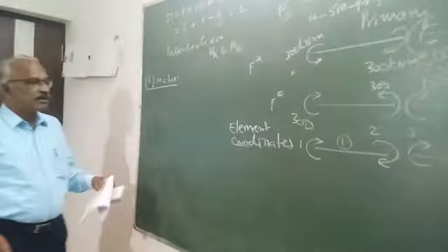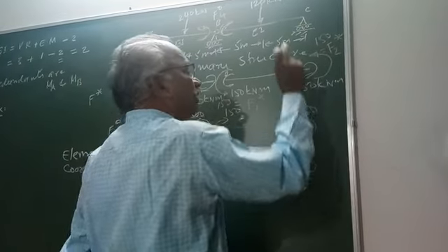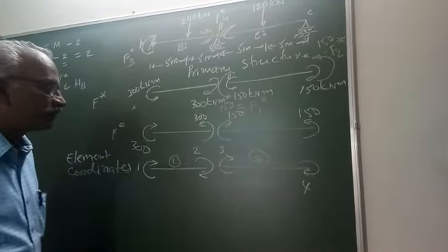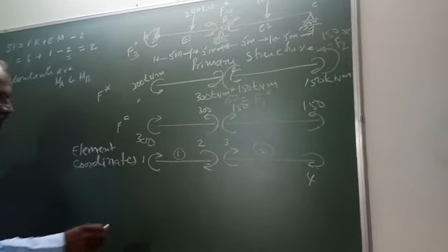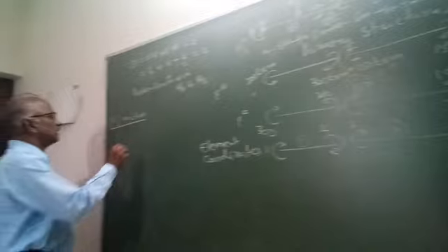We have to apply F1 star equal to unity and find out the values of the forces along the element coordinates 1, 2, 3 and 4. Next step, apply F2 star alone and find out the second column. Like that we have to do, but we will just do the problem. So for getting the first column of the B matrix,